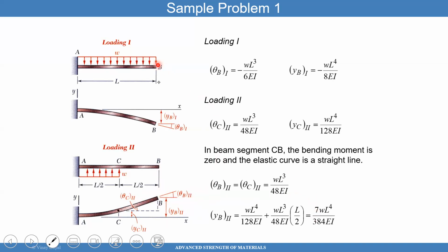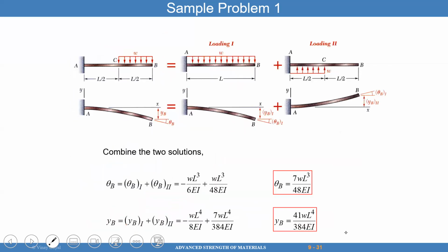You know the deflection at point B from loading 1 and from loading 2. You can add them up to get the total deflection for that problem. And I did it here. Take a look. It's just another application of how you could do this in a visual way. That's another thing I like about this: you can do it visually, breaking up the problem into simpler things to look at. Maybe there's a table that has equations, but you can then add them up and not have to go through the suffering and pain of deriving all the equations one by one.